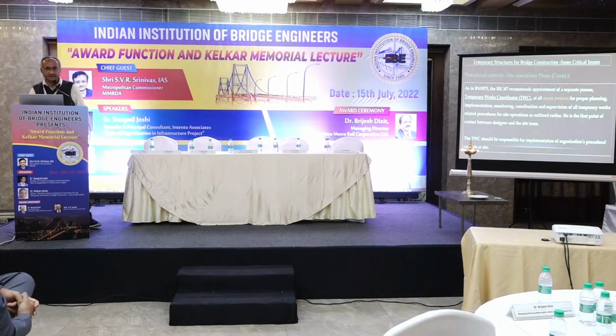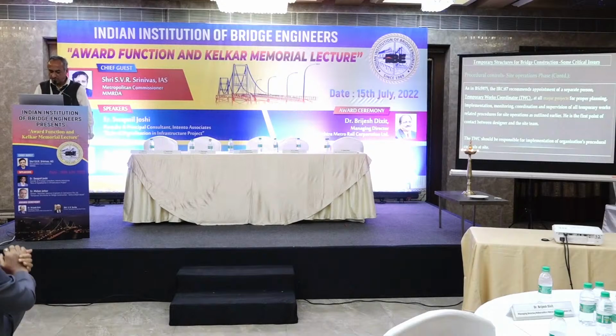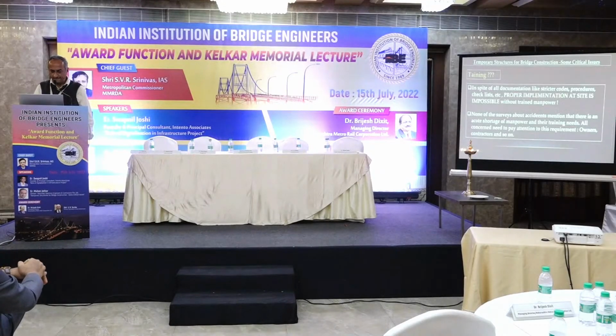The most important thing which it recommends is appointment of a temporary works coordinator, who is of course sitting at site and doing all the coordination for proper planning, implementation, monitoring, coordination and supervision of temporary works, and not design of temporary works, so that there are no gaps between various parties which are involved in the whole process.